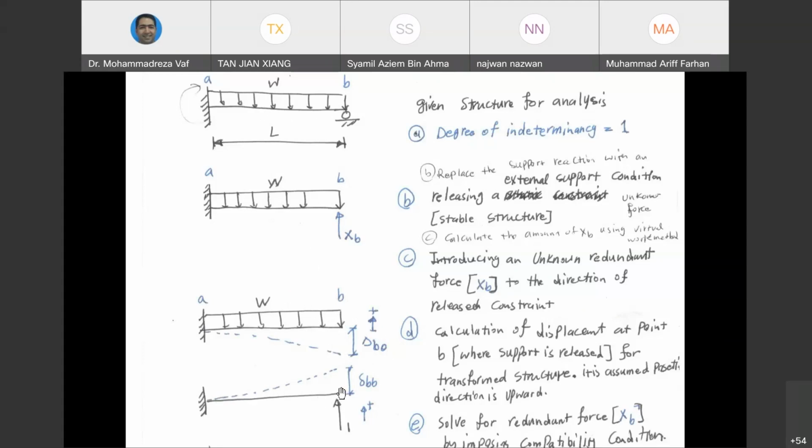But in that beam that I have, there are no external forces. Only a unit load is going to be applied. I will increase the intensity of this unit load so much that delta BB becomes equal to delta BO. In that case, the summation of these two is going to represent the real structure, because I have a structure that doesn't have any deflection. It has the same load, and the support reaction also is going to be equal to